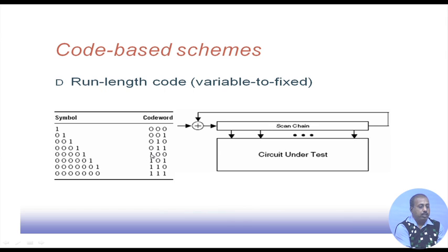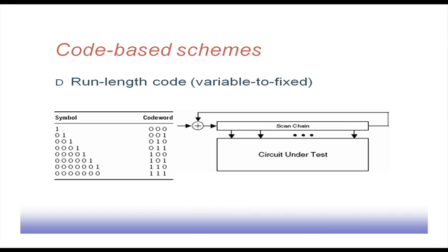So, at the decompressor end, we can recompute the test pattern given the code word information. In the ATE we are storing the code words, and instead of storing large runs of zeros, we are storing the corresponding codes only. That code is getting transferred to the decoder, and the decoder is in turn computing back the original symbol.